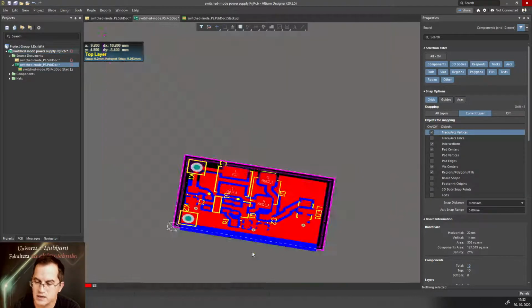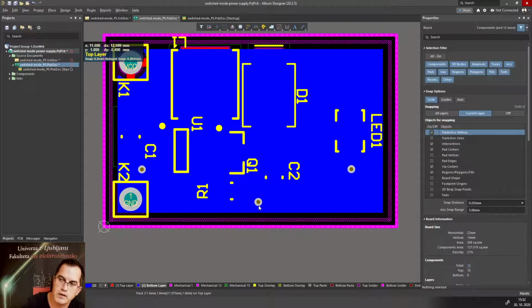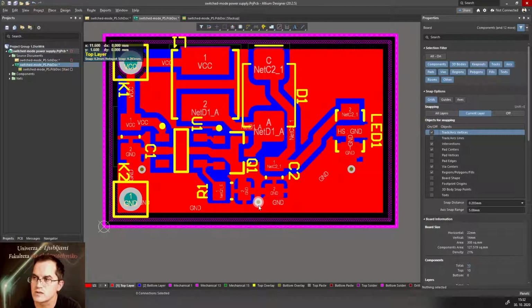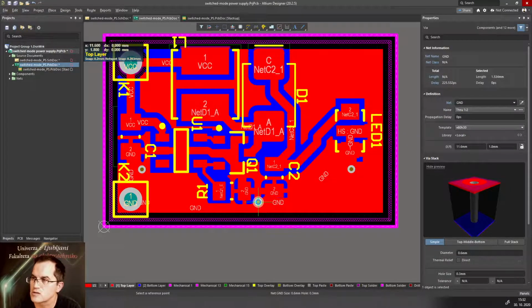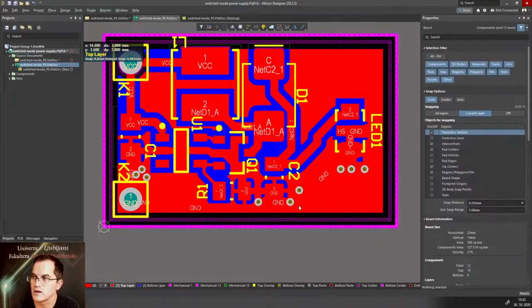And by using big and wide copper planes for current also decreases its impedance. So I would actually go and say use more wires just to make the connection between the components better, so that the connection for this current to run has lower impedance and therefore better connection, lower voltage drops on it. So by using good connection, you can have lower differential to common mode noise conversion.